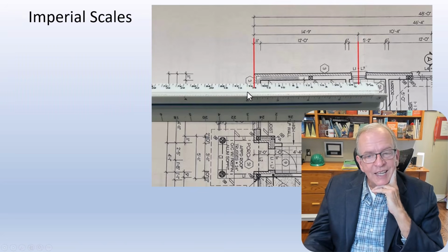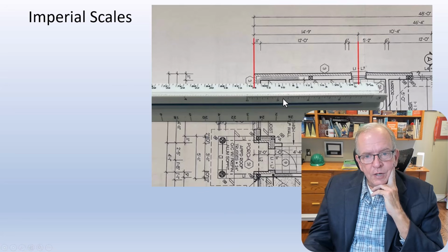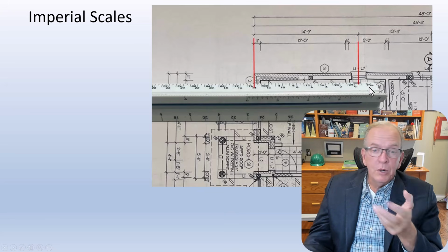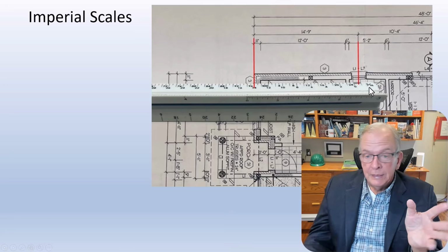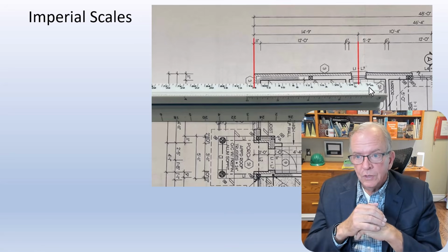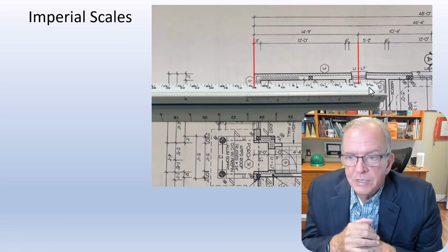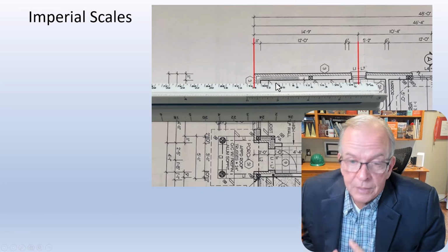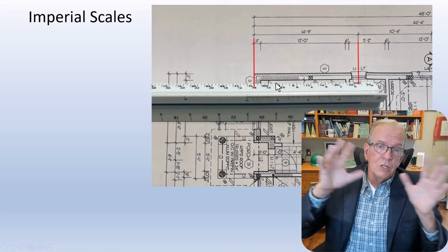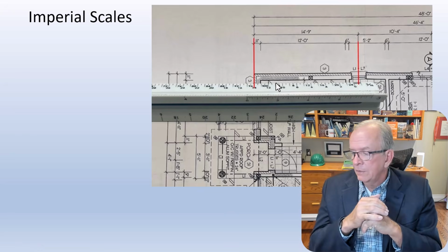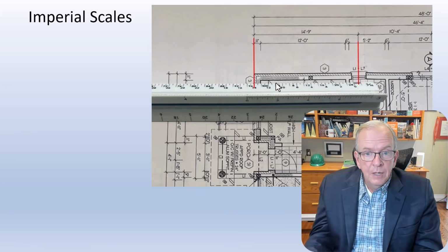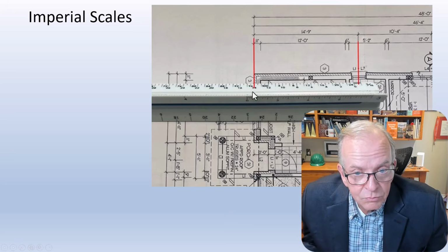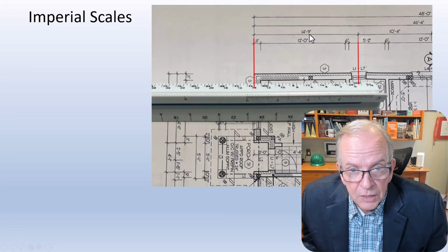So you're basically laying this on a drawing. And so this particular drawing was done to 3/16 of an inch scale. If I wanted to see if it was actually to scale, because sometimes you can have that the drawing was enlarged or it shrunk, a series of things that could have happened. You can check it to see, well, is this pretty good? Because this has a measurement here.